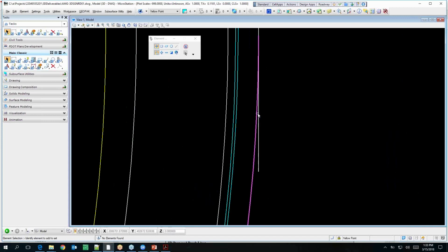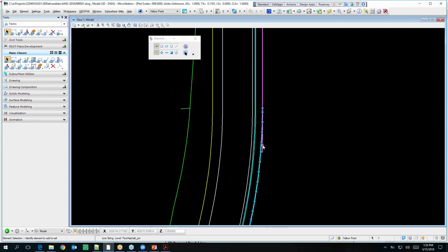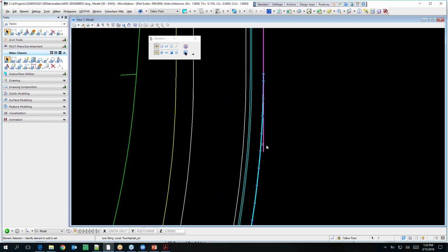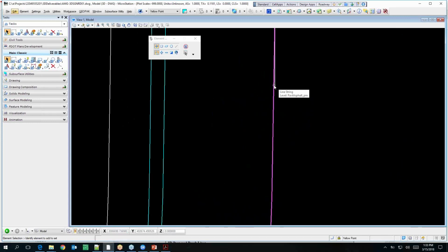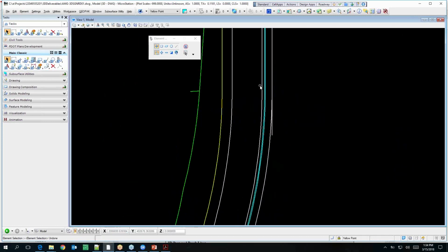Now they're not cleaned up very well though. Why is that? Because they're 3D lines, they might not intersect. Oh, it just clears it to the nearest vertex, doesn't it? I think that's the way it does. I usually just delete vertexes till I get it to where it's close. That's a pretty big gap. Can't I just snap? Theoretically, that'll snap to the 3D position, right? Yep. So you could also do that. Just be aware that that is potentially changing the elevation of the other line. The other thing you can do is extend it, trim to extend, and just go near.